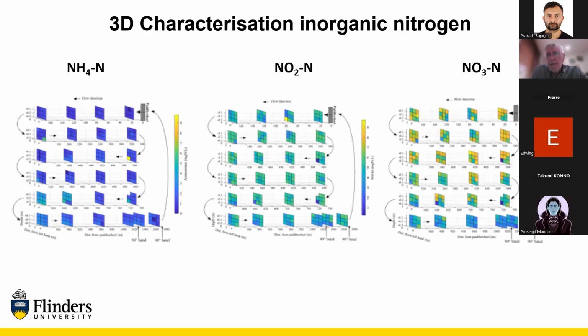And I've put it in the order, if you like, of oxidation. So most of the wastewater coming from the anaerobic pond will be ammonia, NH4-N. We always report our results as the atom of nitrogen in this particular inorganic nitrogen, because then it's very easy to do a sum. We can just add this up because we're only measuring the atoms of nitrogen, small point.